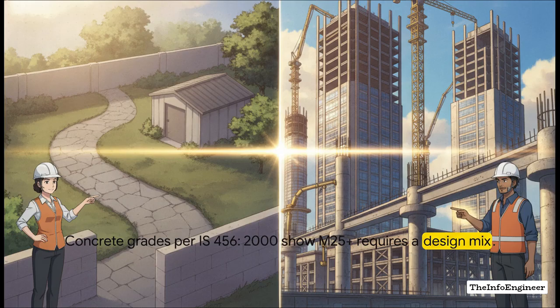If we take a look at the concrete grades based on the IS 456-2000 standards, there is a really clear dividing line. Nominal mixes, they're generally totally fine for your ordinary grade concrete, basically up to M20. We're talking non-critical, lighter projects, pathways, simple boundary walls, that kind of thing. But the very second you step up into standard and high-strength concrete, so M25 and above, the codes essentially demand a design mix. I mean, for load-bearing beams, high-rise columns, heavy structural elements, you just absolutely cannot rely on assumed strength. It's way too risky.